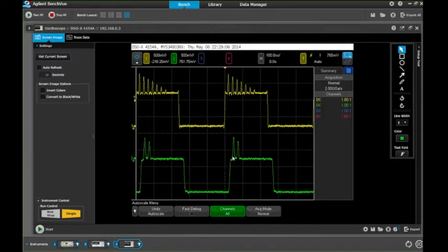So what you can see now is, again, the Trueform generator outputs our 7 points. And now, all of a sudden, our DDS-based generator is skipping some of those glitch points that we had. Both signals are looking a little bit noisier because we are sampling faster, but we can obviously see that the DDS-based generator is missing some points. So that's one of the major flaws with a DDS-based generator, in that the higher the frequency goes, the more points you're going to skip, and it's going to be more obvious.